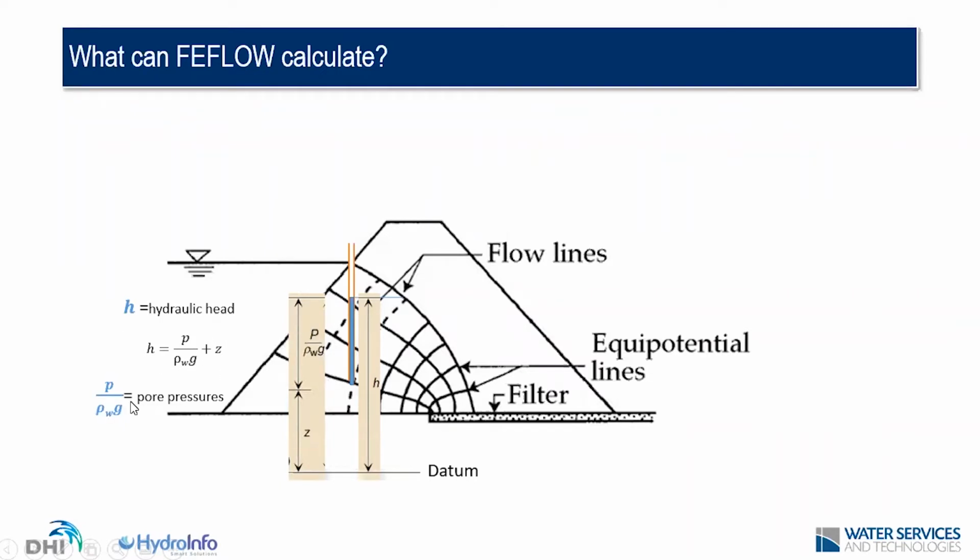And so FEFLOW can give you at any time not only the heads but also pore pressures, which is the parameter that you need to feed a geotechnical model in order to use as a parameter for the stability analysis, along with Young's modulus and the other parameters that geotechnical models use.